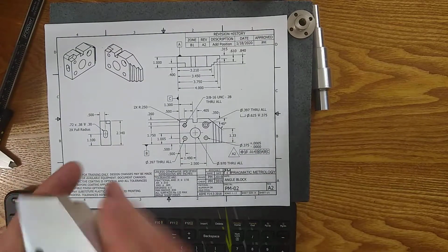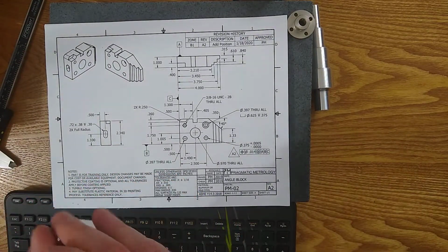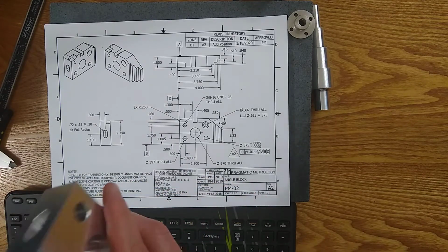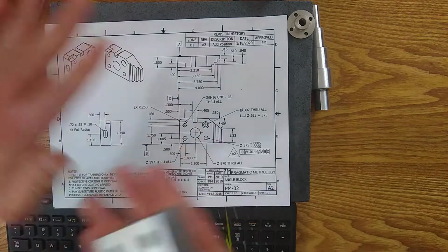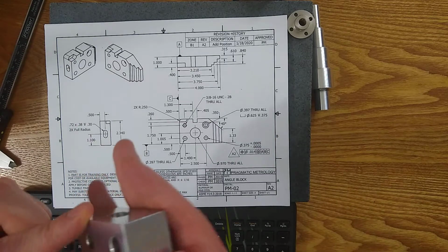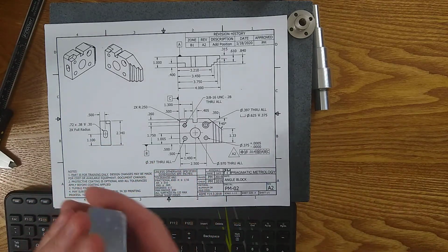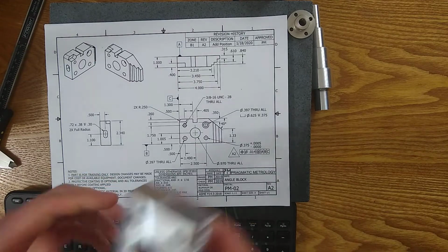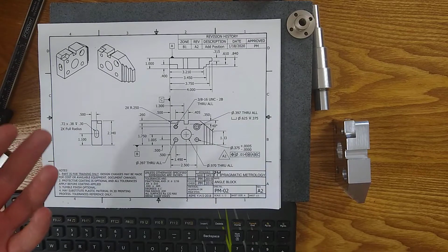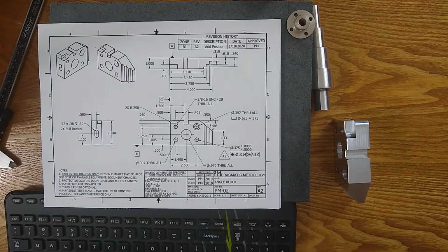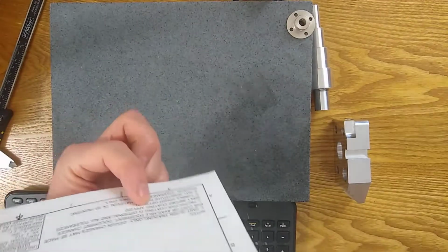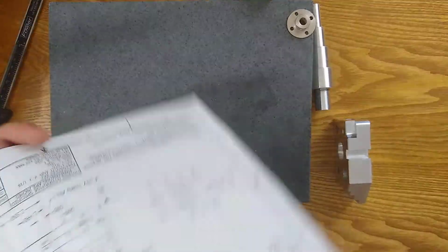Surface finish or coating: if you're supposed to have a special surface finish or a special coating, sometimes that gets overlooked. Masking: if there are threads involved, or certain assembly surfaces, they may want to mask those off. You're going to look for bleed, look for anywhere where the masking came off, and make sure that they masked it correctly. And then of course special instructions, which will be special handling, special inspecting instructions, whatever it might be. But those will usually be notes or be on the job traveler.